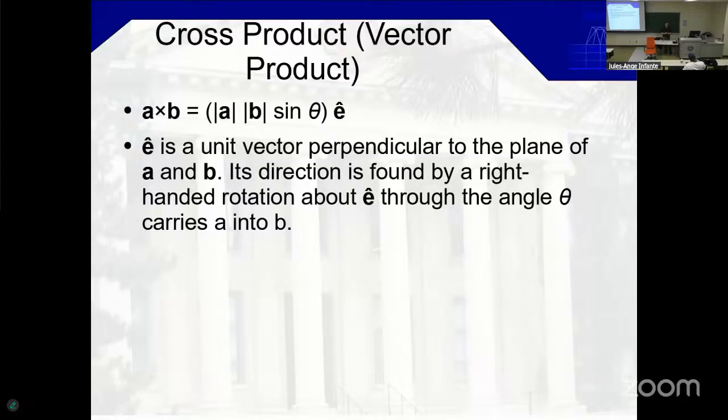They have station 0 and then they will move. They have stations and offsets, okay? When you're talking about roads, on a given segment of the project that you are dealing with, you will have the easting and northing of control points, but the project coordinates, okay? Once the control points are there, just to reference your job to the overall world, the job itself will be in terms of station and offset.